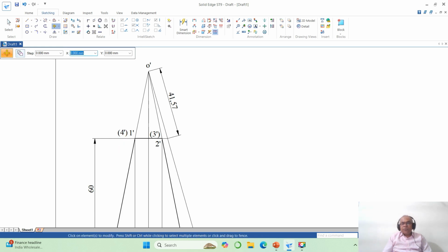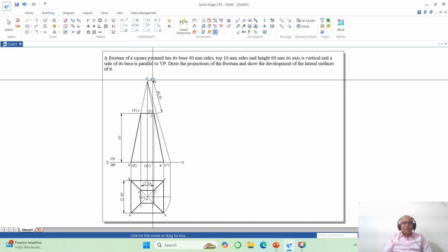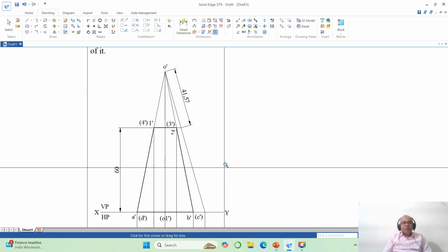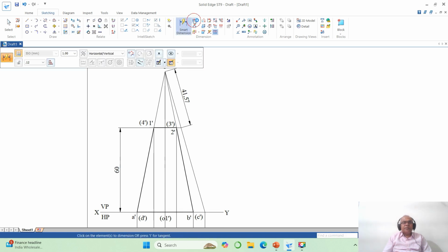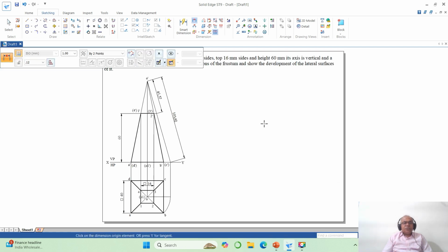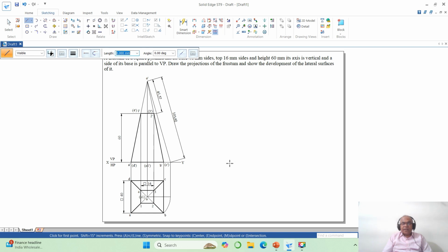Okay, now you go to fit, come down to zoom window, then you go to distance between, select endpoint of this to endpoint of this, you take 103.92. Yes, correct. So once you do that, you go to fit. Now I need to consider this as the point. So to do that, I will go for a line.